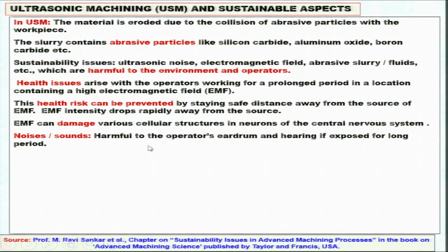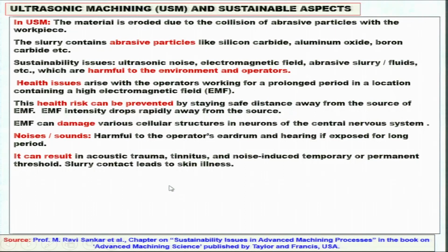Noise is harmful to the operator's eardrum and hearing if exposed for a long period, because ultrasonic vibrations, ultrasonic noise is there, which is harmful to the ears. It can result in acoustic trauma, tinnitus, and noise induced temporary or permanent threshold shift.